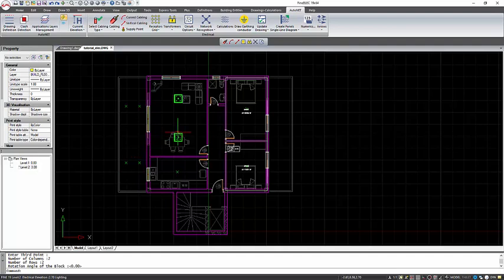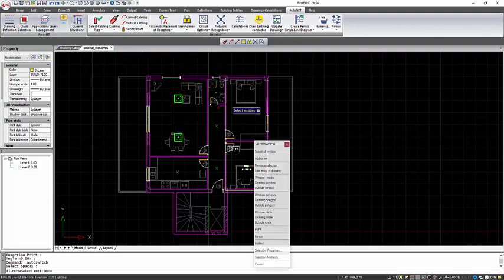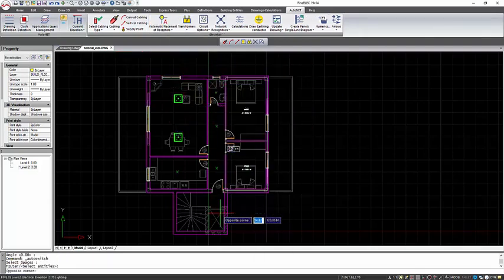It is possible to install the receptors automatically in a room with defined space in the plan view. The command requires that there is a door that opens inwards in the room. Then, the receptor is placed on the side of the wall that is opposite to the door hinges.